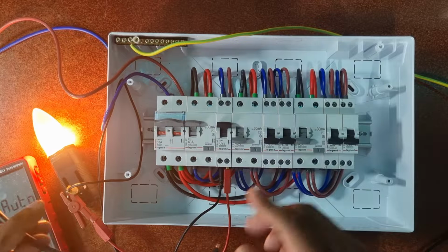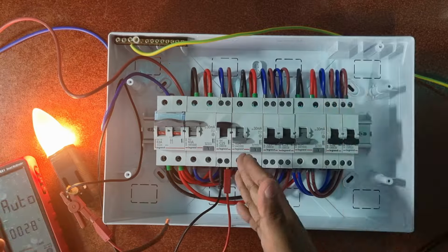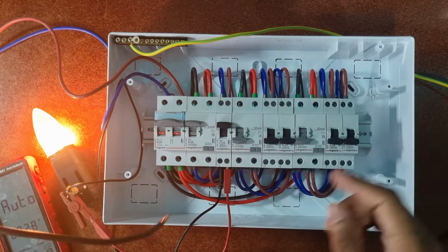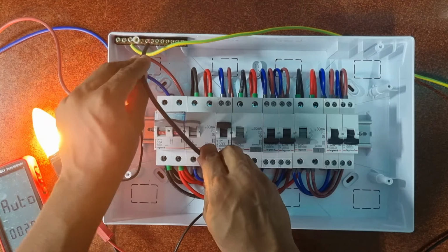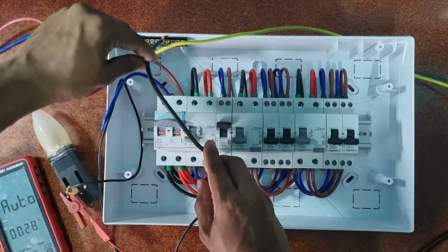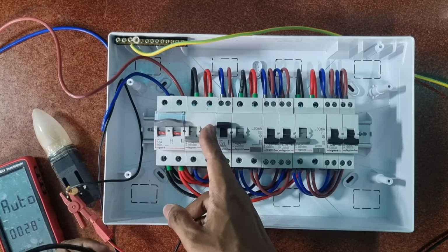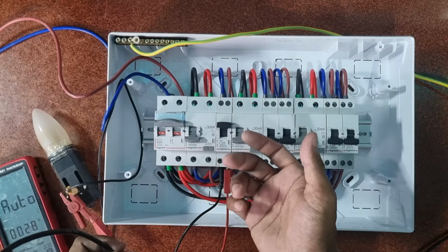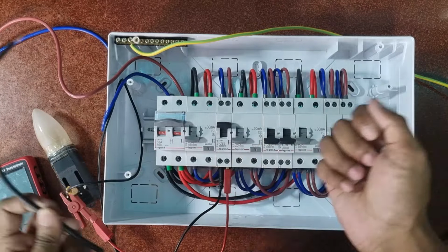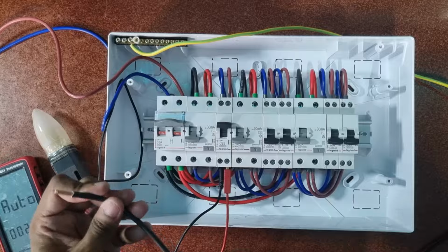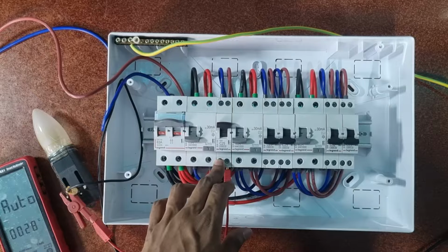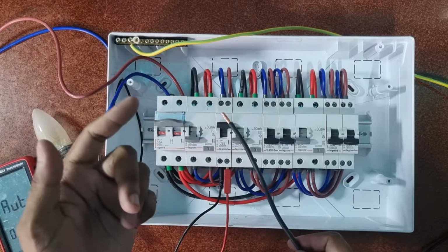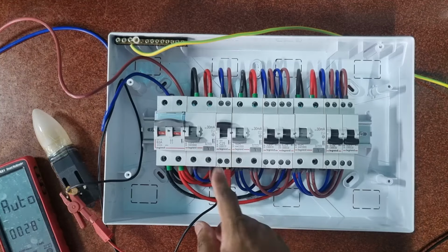Now let's do the fault test. The fault test is basically you have a leakage between neutral and earth. So if there's any leakage, let's say my neutral to earth here, look what will happen. My RCD trips. So this is very important to have. The leakage can be as well if I touch the wire with my bare hand. If I touch the wire or any electrical appliance in the house, once the current goes through me, the RCD will trip immediately. So you will get a very little shock, but you won't be electrocuted. This is very important.